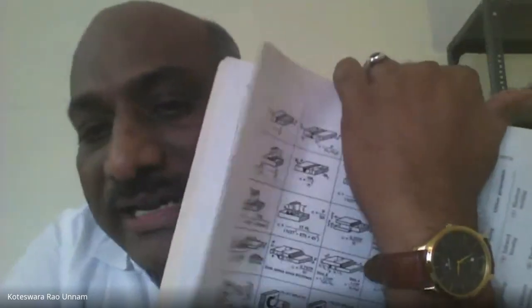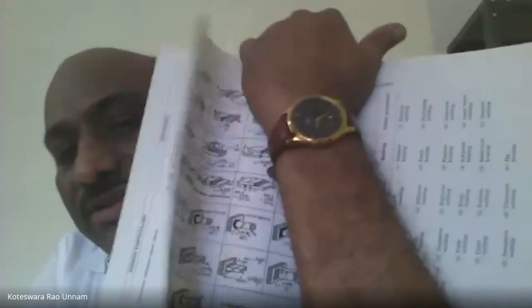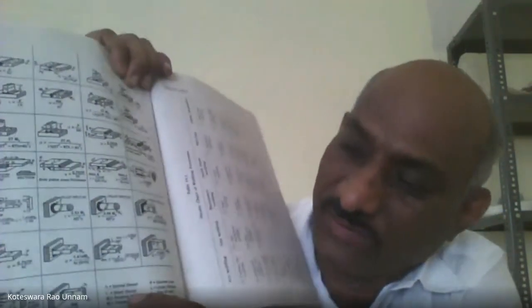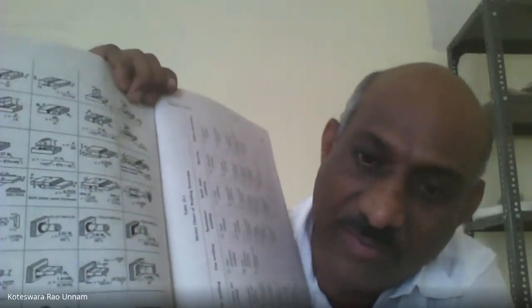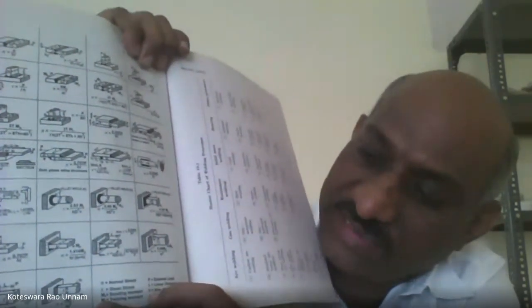In our presentation, what I have shown you, I use T. Here he is not using T; he is using the symbol H. In the description at the bottom he has given: sigma is normal stress and tau is shear stress, M is bending moment, MB is bending moment and MT is the twisting moment, P is the externally applied load, L is linear distance, H is size of the weld, and l is length of the weld. So you have capital L and small l. Capital L is used for the linear distance, small l is used for the length of the weld.